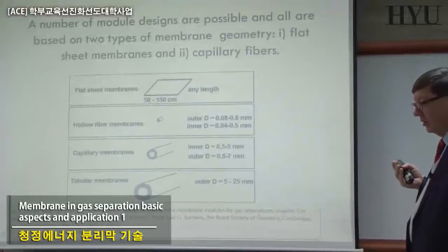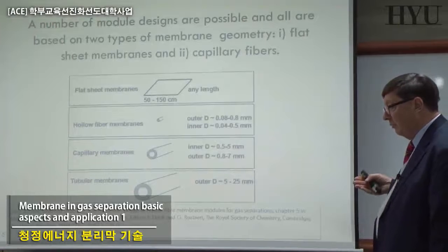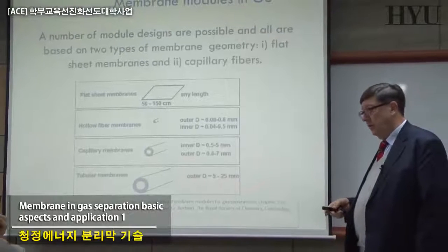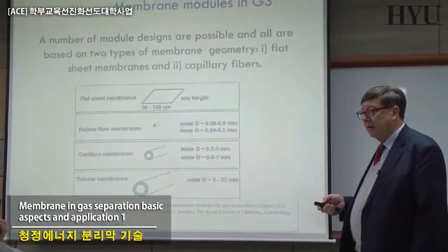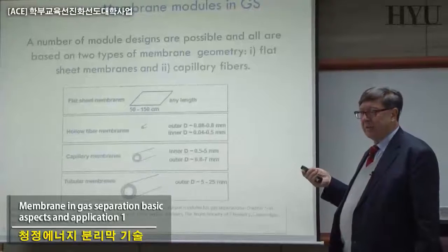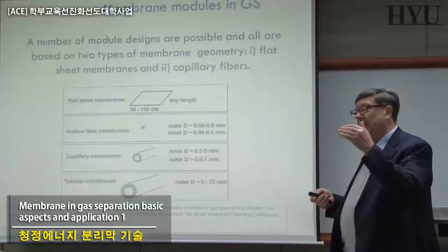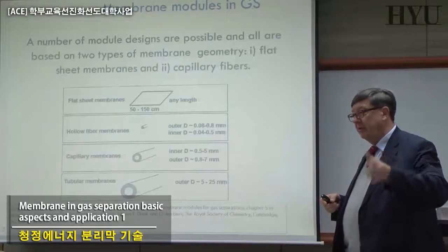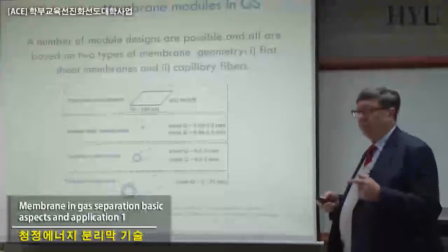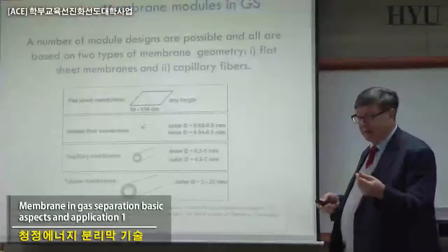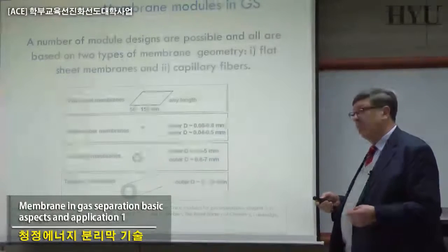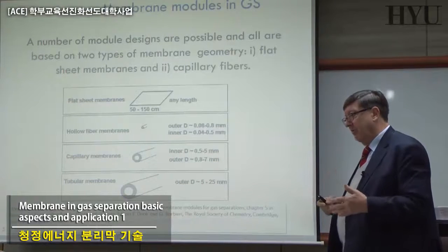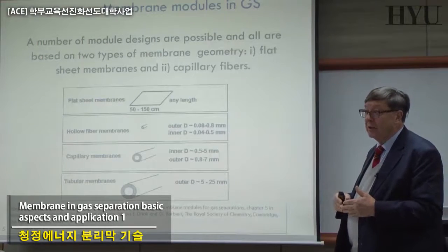And the reason was that initially the idea is that the same problems that are creating trouble in reverse osmosis or in liquid operation are less severe in gas. Gas is much easier to clean and to pre-treat. If there are some particles, etc., there are already systems in which you can easily reduce the percentage of contaminants and particles present in the gas, and the number of other chemicals present is normally much smaller than the one you can have in a liquid system.